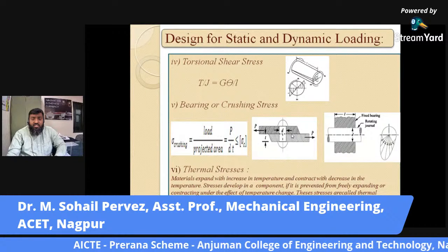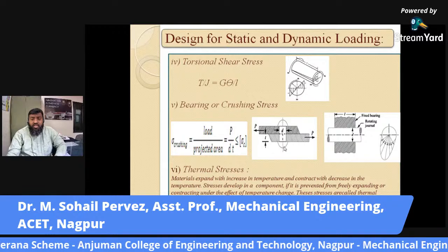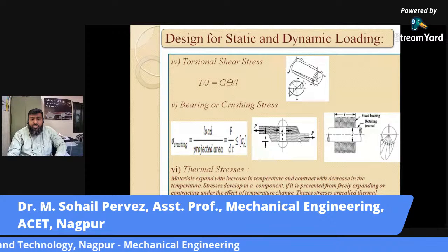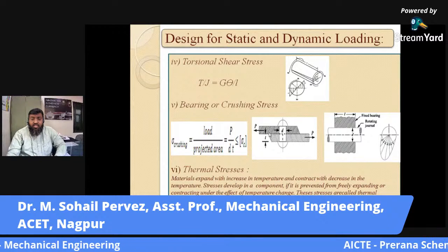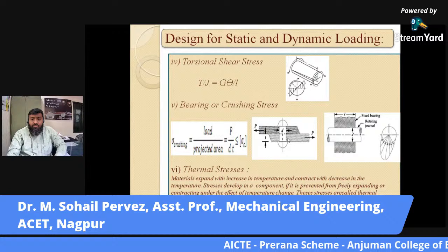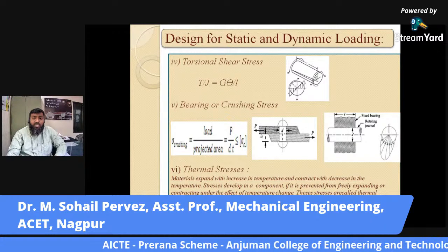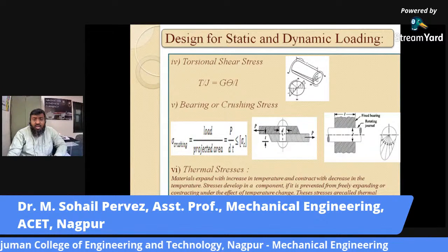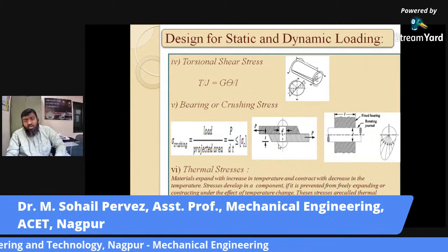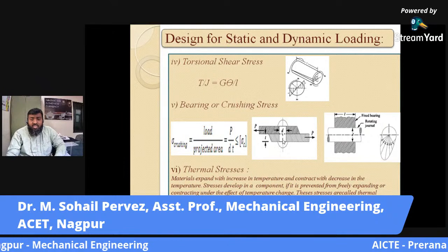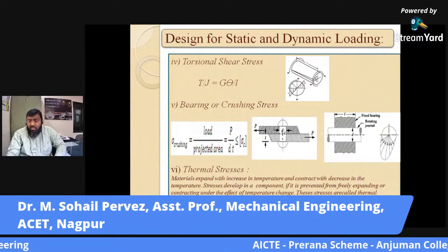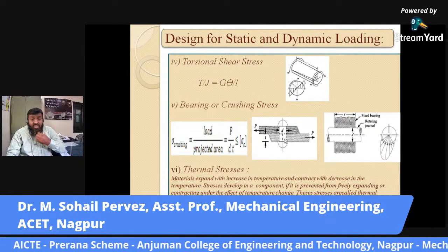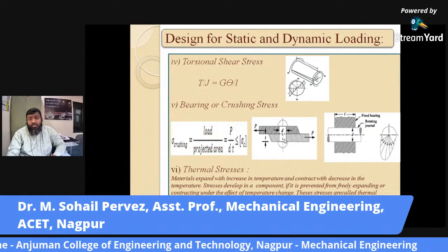by considering an example of two plates riveted by a single rivet, when tangential force is applied in two different directions, this rivet may fail along this joint of two plates or along one single plane. It is known as single shear. If this rivet fails along two different planes, then it is called double shear. In single shear, we have got two pieces of a rod or a shank of that particular rivet, whereas if we are getting three pieces, we may say it is a double shear.